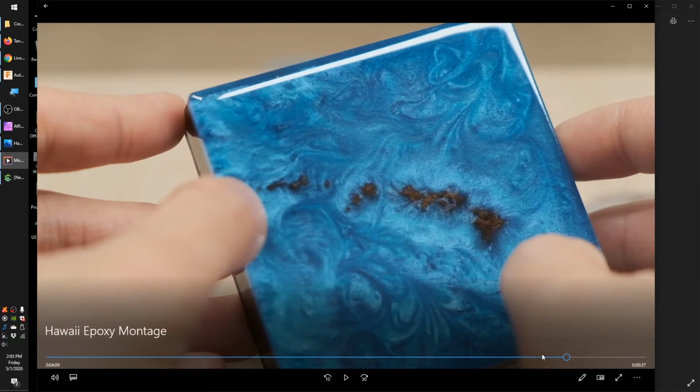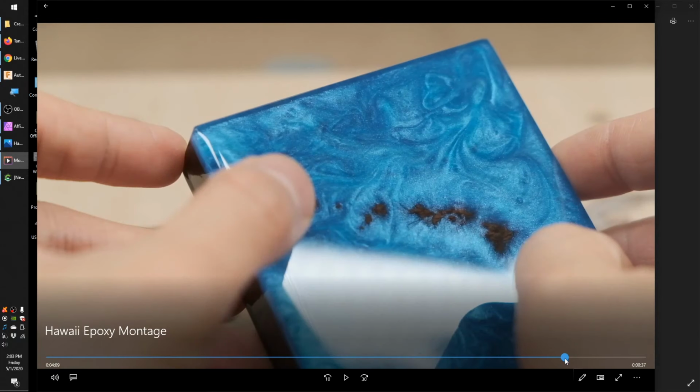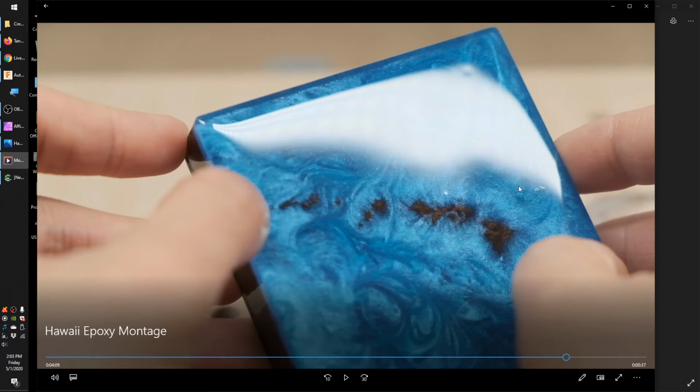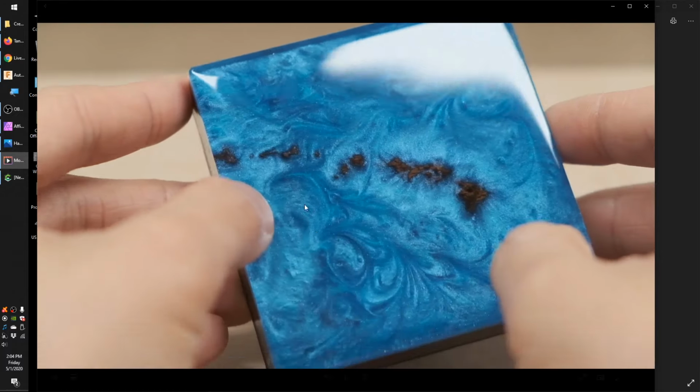Let me try and catch the light at the exact time. So there's a flake on the right side of it where I think I was mixing in a used container. So I had a little chip of old cured epoxy go in with everything, and I didn't notice it. There's a couple specks of dust in here because I was letting this cure in my CNC enclosure. Terrible idea. You should try and do this in a nice clean place if you can.